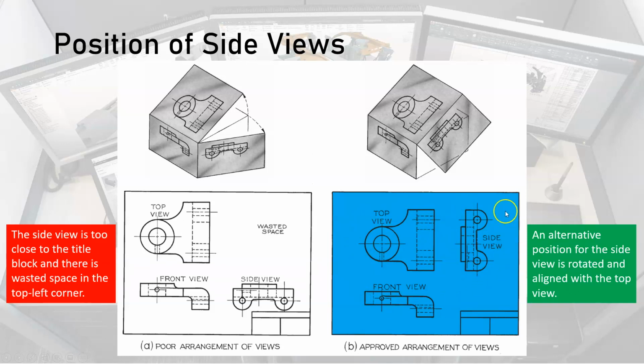We clearly have enough room for dimensioning. We're not crowding the title block. Okay. So where you have the option, you should definitely choose your view arrangement wisely. Okay. To use space in a good manner.